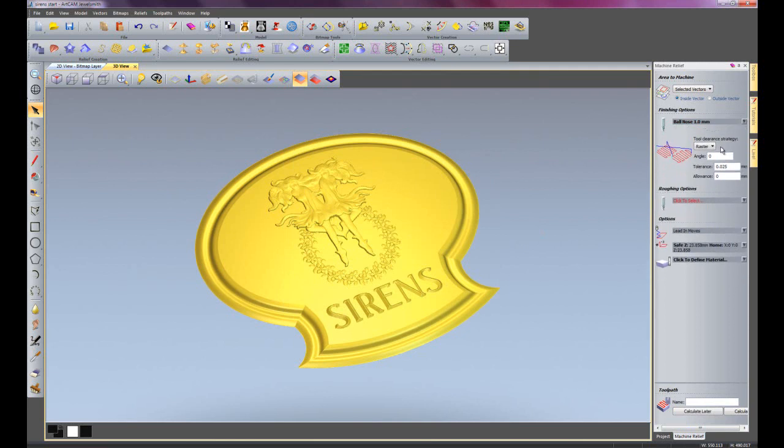a little bit faster. Here we have all of the tool clearance strategies. So there you can see lots of different strategies. The raster and raster classic, a lot of people ask us what's the difference between raster and raster classic.